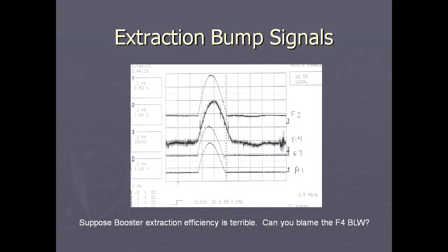But the amplitude of the bump of an individual, the current from it, these are all currents, incidentally, because you can get the voltages too, and that will mess you up if you don't know what you're looking at. The amplitudes will be drastically different, usually much lower. And so you can fool yourself with a scope setup. You say they should all be equal, and then you go crank, crank, crank, just trying the gains on every one of them. It's very easy in a fast scope setup, and then you say, no, that looks beautiful. It looks just like the reference picture.